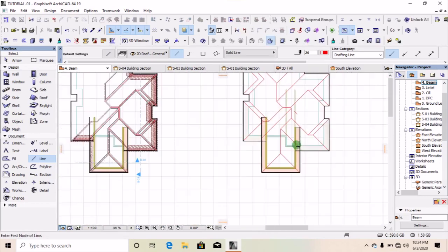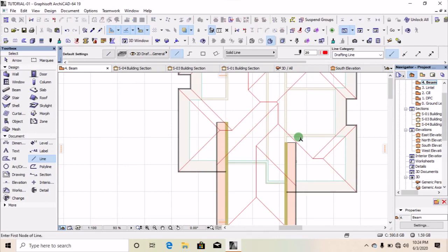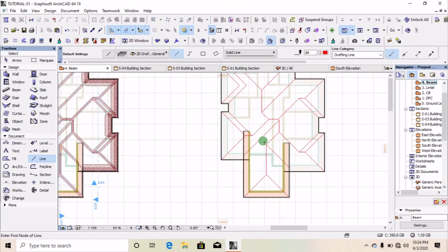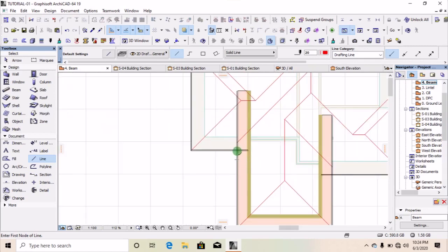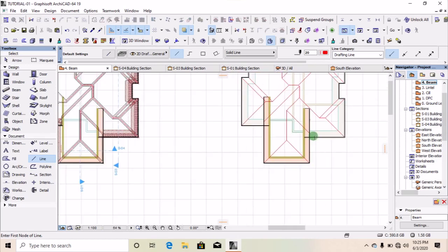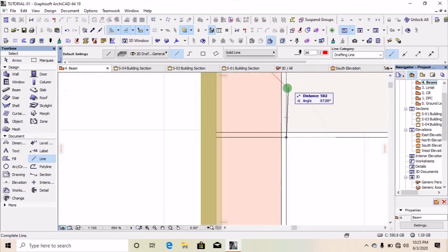From what we just did, you can see how to draw the roof outline of a roof that has different levels. You don't take from this spot. What you simply do is draw a line equivalent to the height difference of the levels, which is 500, and stop at this spot, then take your angle from that spot. If you check from this place to here, you have 500.